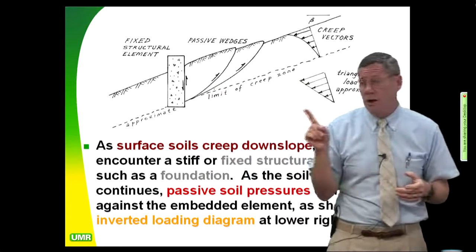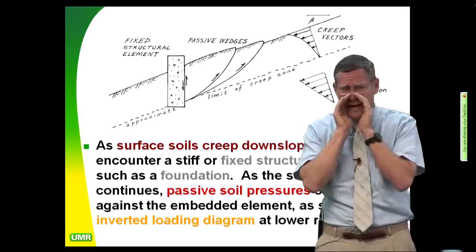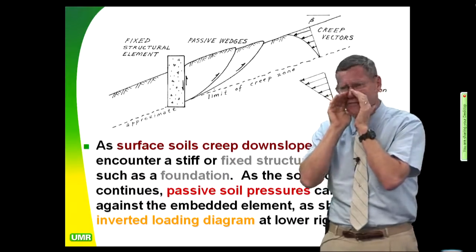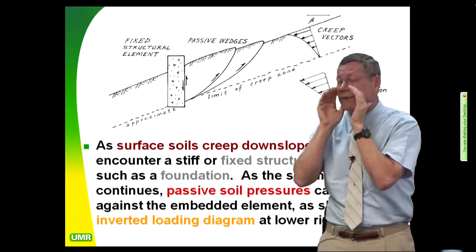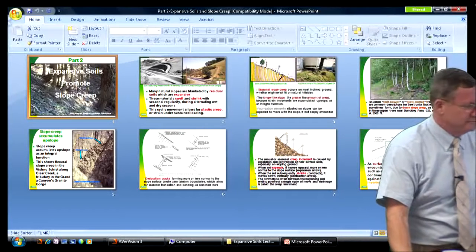If you're going to do a block wall, by the way, put all kinds of drainage behind it. You never can have too much sub-drainage. You can't have too little. You never can have too much sub-drainage. Okay? All right. So we're done with that little vignette.